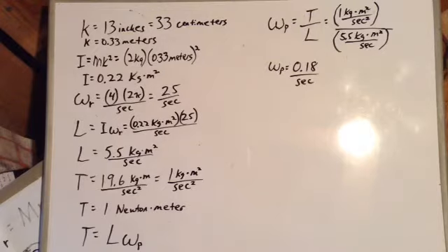Let's say this bicycle wheel is a 26-inch bicycle wheel, and let's say it has 2 kilograms of mass. So most of the mass is in the tire tube and rim. The mass of the spokes and bearings is relatively insignificant. So let's say its radius of gyration is 13 inches. 13 inches is 33 centimeters.